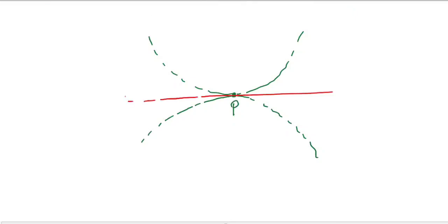Suppose, Anjali, this is my pitch circle 1. Okay. And this is my pitch circle 2, na? Okay. So I told you that there is a point, pitch point P, and from this point there is a horizontal tangent. Okay, and the component which I was talking about is lying in this way, actually. So this line is what I drew just now. Here is the F force. So the common tangent and this line of action, this angle is known as, Anjali, what? Pressure angle.